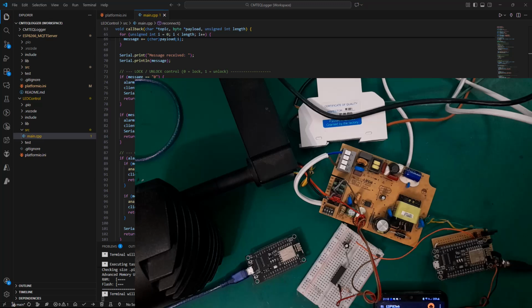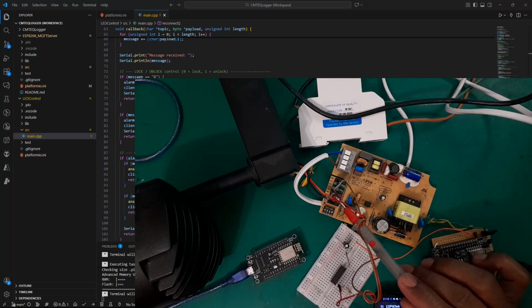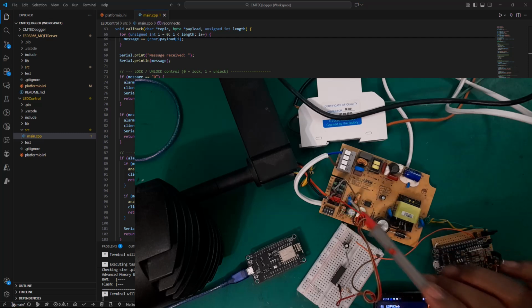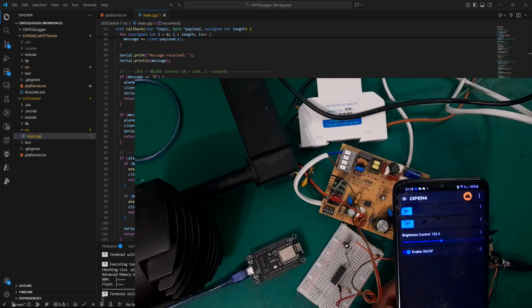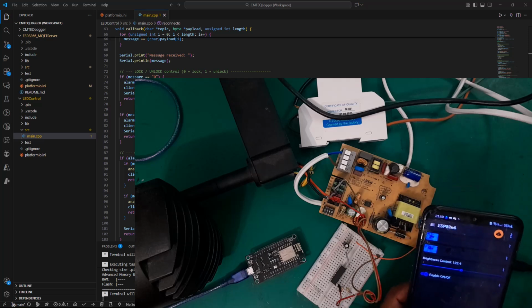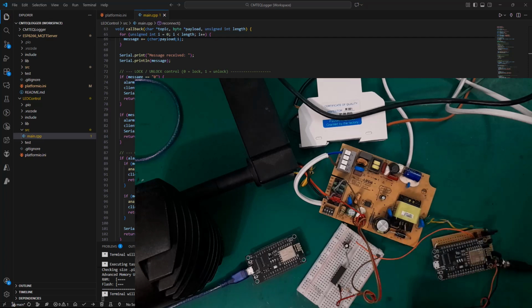integration. So instead of dimming directly by applying an external power supply into the dim plus and dim negative, we're going to bring the power supply into the ESP device here, okay? And the ESP device is just not going to dim the light by itself. It's going to be receiving commands. The commands are going to come from the cell phone application here that is creating MQTT topics so that you can send commands. Then obviously these commands need something that must handle them. So that is the MQTT broker.